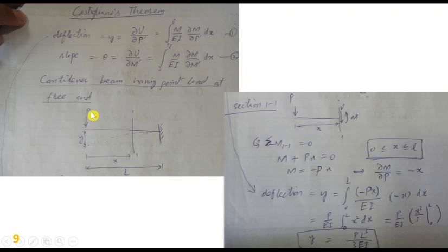So if the value of P is given like here, we will not use the value, we will use the symbol, because we have to take the derivative and integral that way. First of all, and in the last step we will put the values. So, if force is not here, it is applied somewhere else, then we will apply a fictitious force P prime here, a supposed force P prime here, and we will do the procedure as stated in this problem.